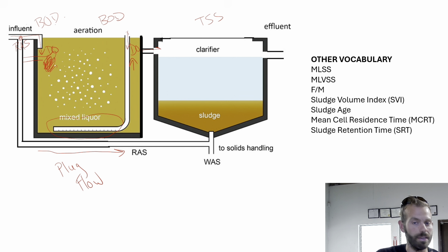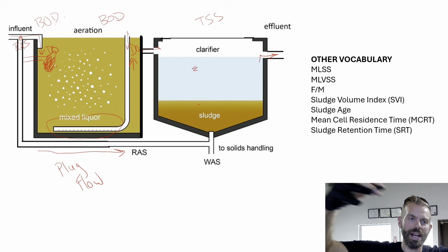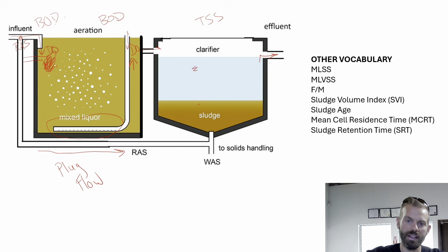Or if you have it Goldilocks, and this is wastewater treatment just right, Goldilocks, you should have an incredibly clear effluent on the top, or the supernatant actually. It's not the effluent until it leaves the clarifier, and then you should have a really well compact but not super oxidized sludge at the bottom of the clarifier. Okay, and that's where your TSS is resolved. That floc kind of just grabs all those solids to itself, and it's adsorption, but for the sake of this conversation, let's say it just kind of creates a net and pulls it all down with it, and it leaves this really clear water on the top. Okay, that is it in a nutshell, but now we have to deal with this sludge, okay?